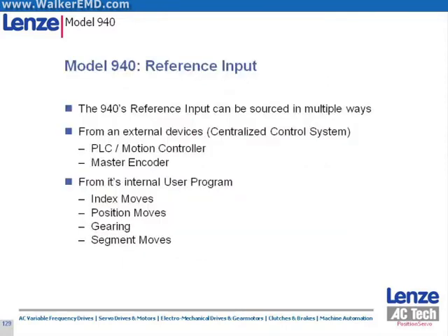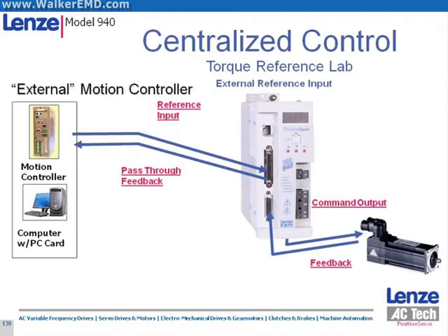Reference can be set to either external or internal. An external reference can originate commonly from a PLC, a motion controller, or a master encoder. An internal reference originates from the drive's internal variables. These typically are manipulated by the internal user program, but can also be written to from a master device over a communications network.